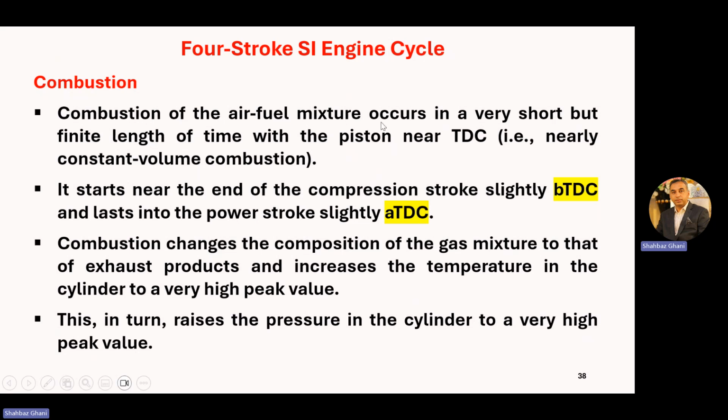Combustion of the air-fuel mixture occurs in a very short but finite length of time with the piston near TDC, nearly constant volume combustion. Remember this thing: it starts near the end of the compression stroke slightly before TDC and lasts into the power stroke slightly after TDC.